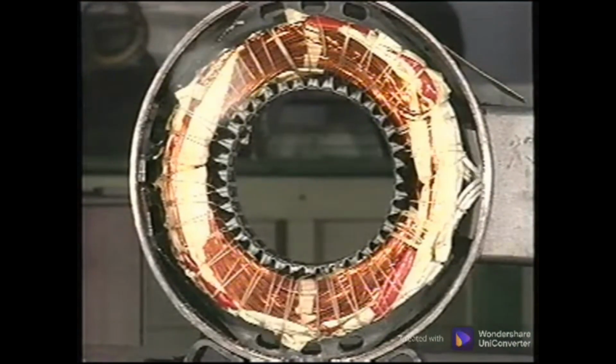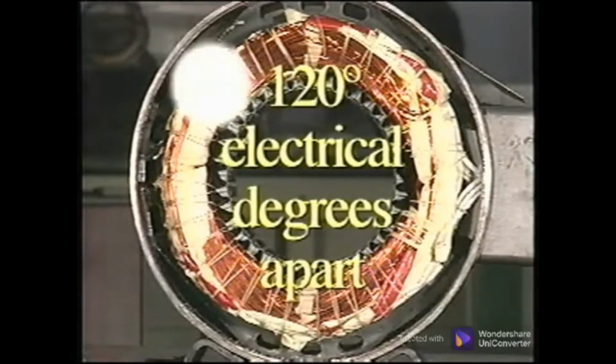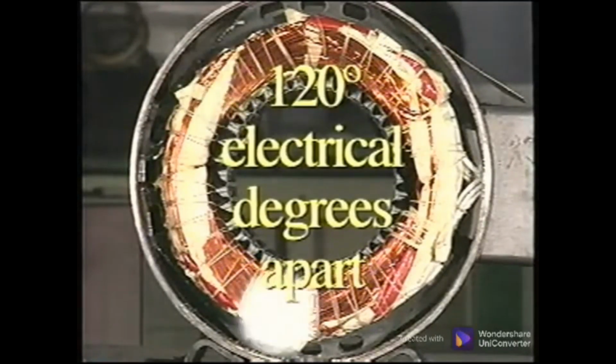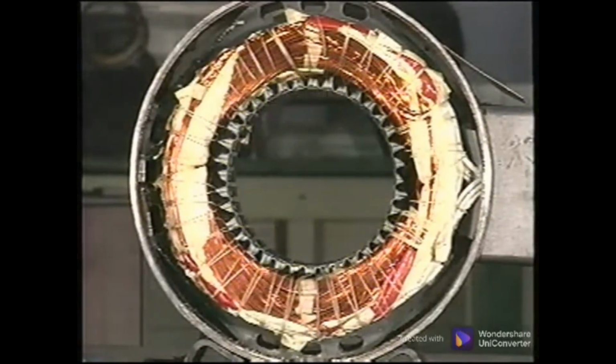When a three-phase stator is connected to a three-phase source, three independent currents flow, one in each of the phase windings. These currents are displaced from each other by 120 electrical degrees. This 120-degree separation in time between the phase currents produces the stator's rotating field.